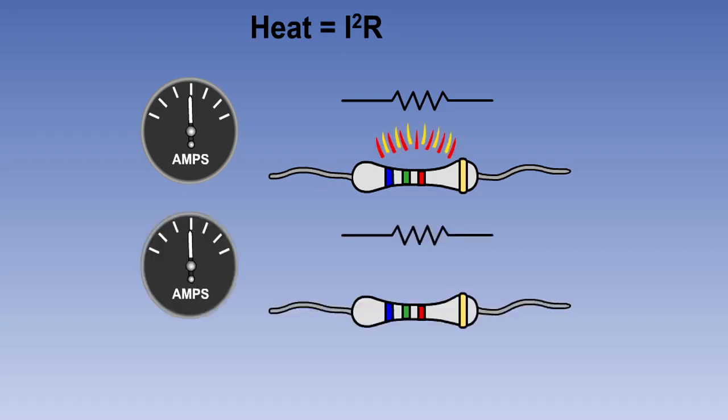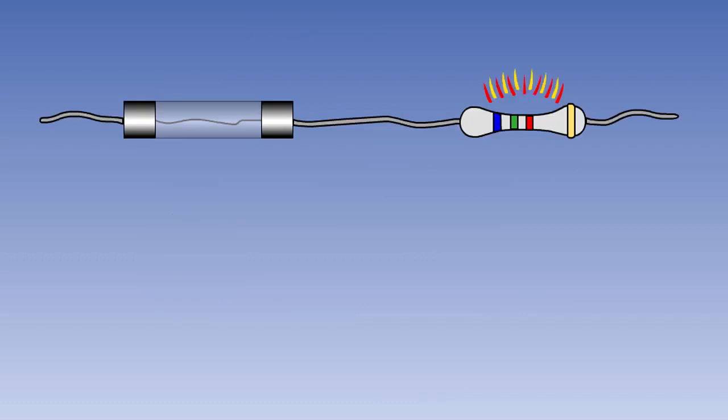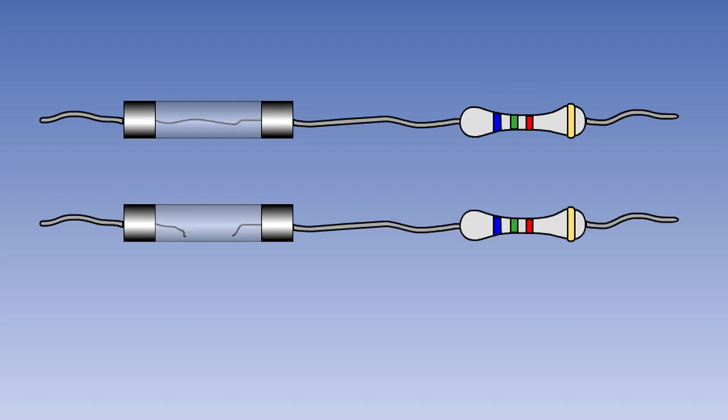Each electrical component, and the wiring which supplies it, is given a power rating or maximum wattage, which, if exceeded, will cause it to overheat. Each electrical circuit in an aircraft will be protected by a fuse or circuit breaker, which will prevent the maximum permitted current flow in the circuit from being exceeded by breaking the circuit if the current increases beyond a safe level. Fuses and circuit breakers are described in another lesson.